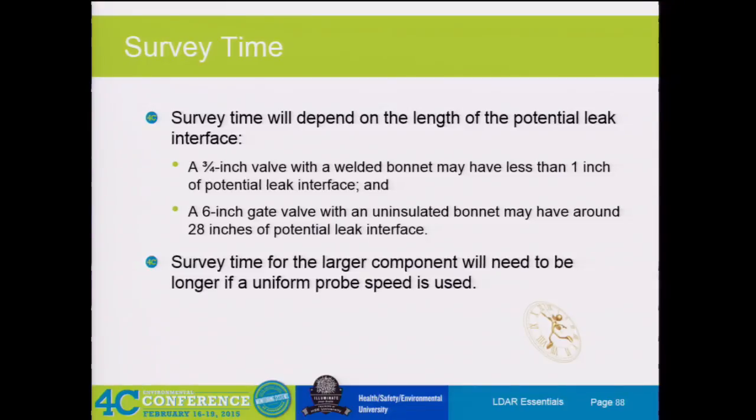We have clients who said, I'm just putting 60 seconds for every component out there. They're going to spend 60 seconds monitoring it. I don't think anybody should go to that level. If you have a big valve, you should spend more time than if you have a 3/4 inch valve. There's a big difference between 1 inch of potential leak interface versus 28 inches.